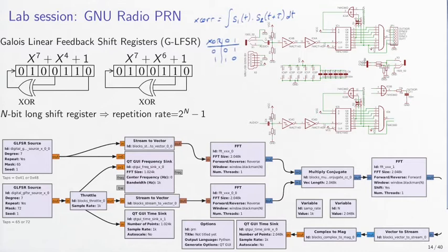How do we integrate over time? This is this low-pass filter over here. So this low-pass filter will be the integral over time here. So we do a multiplication using the XOR, and the output will be low-pass filtered, and this is the integral dt. So the actual hardware implementation of the integral of S1 times S2 is taken care of by this XOR function and its low-pass filter. So let's look at how this signal looks on the practical output.